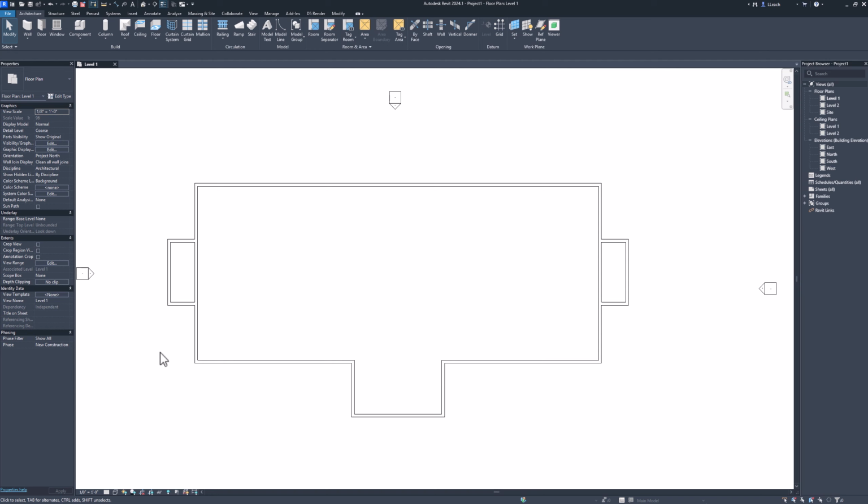All right, so the next thing that we're gonna do is we're gonna create a wall type. So many times when you're using Revit, you wanna use a wall and Revit doesn't already have that created. So instead of creating a brand new wall from scratch, most times what you can do is take an existing wall type, make a copy of that wall, and then rename it, and then make edits or changes to make it the wall materials that you want. So we're gonna kind of show an example of that here.